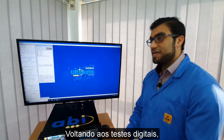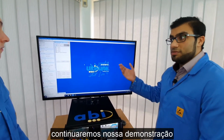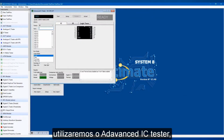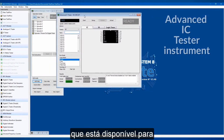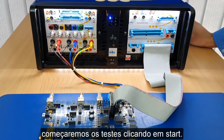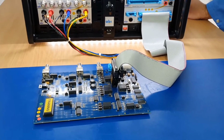So moving on back into the test itself, again, we're going to use TestFlow. We will continue the TestFlow we have here. And we're going to be using the advanced IC tester. So the advanced IC tester is one of the instruments that comes along with the BoardMaster and specifically used by the ATM, the advanced test module. So what I'm going to do here is simply start my test.